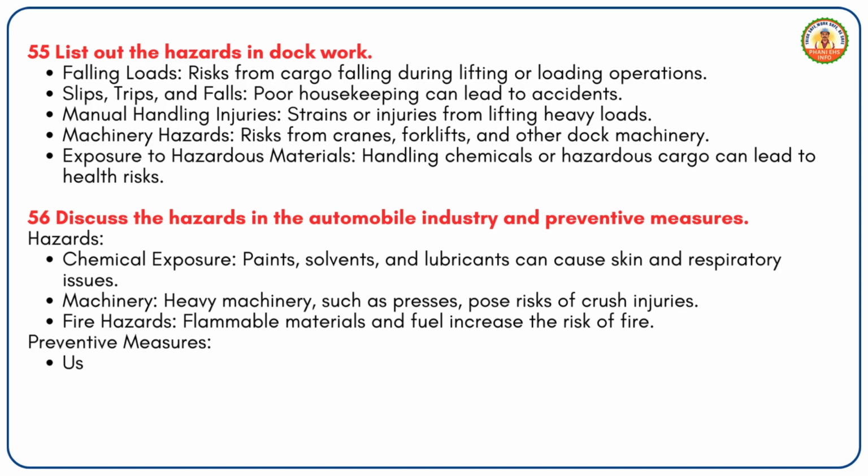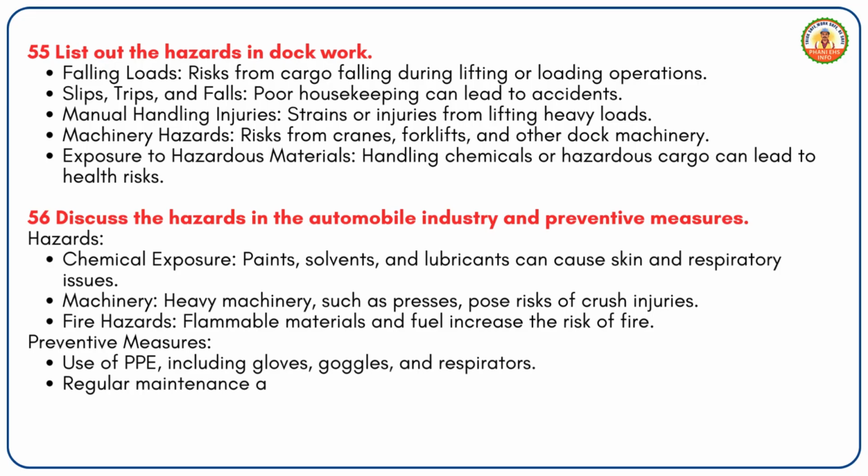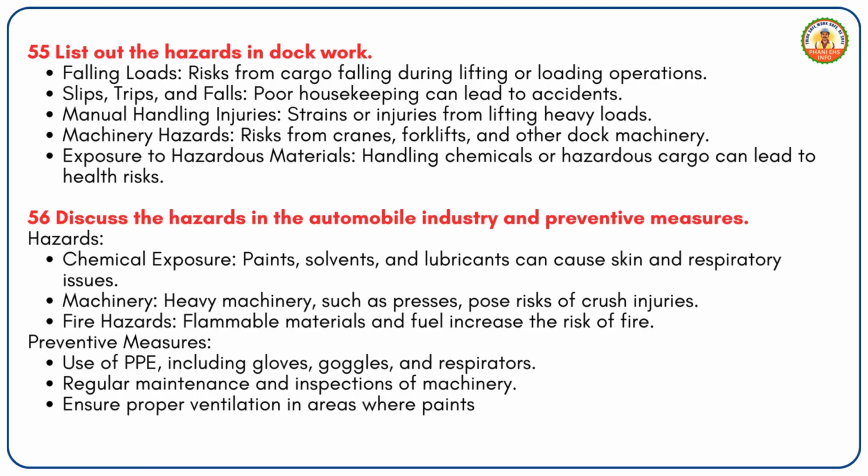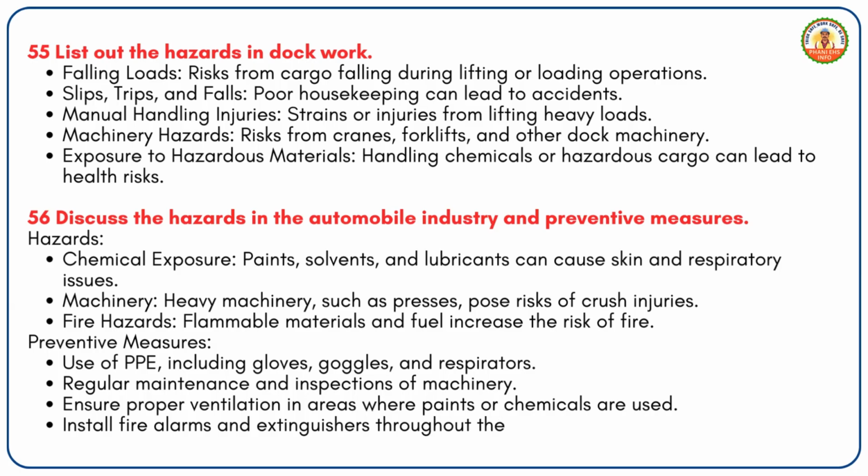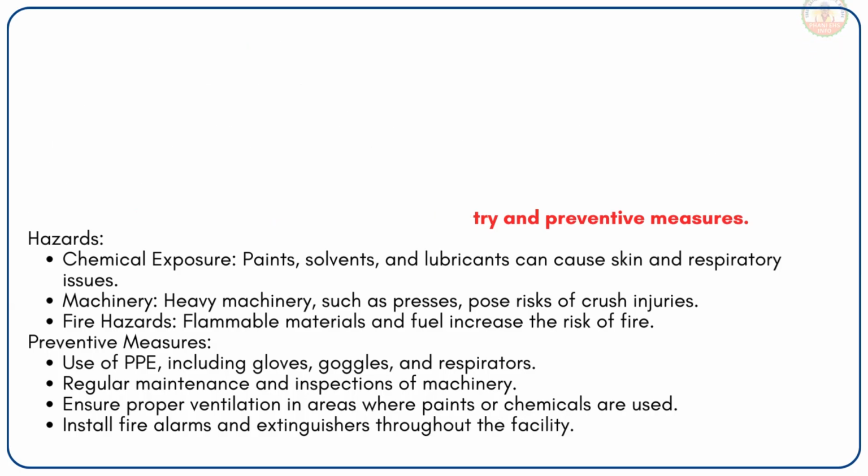Preventive measures. Use of PPE, including gloves, goggles, and respirators. Regular maintenance and inspections of machinery. Ensure proper ventilation in areas where paints or chemicals are used. Install fire alarms and extinguishers throughout the facility.